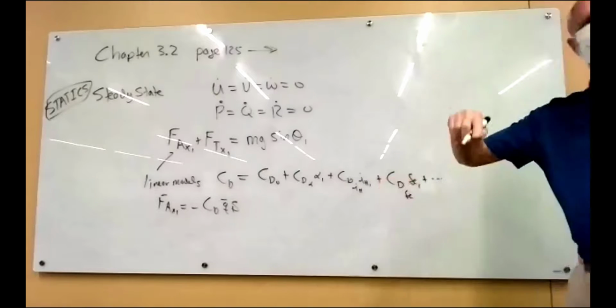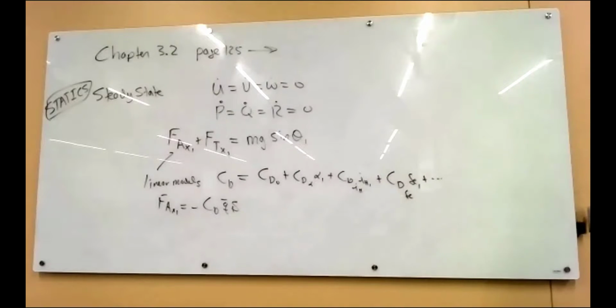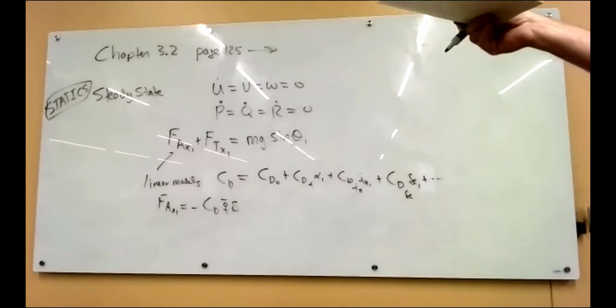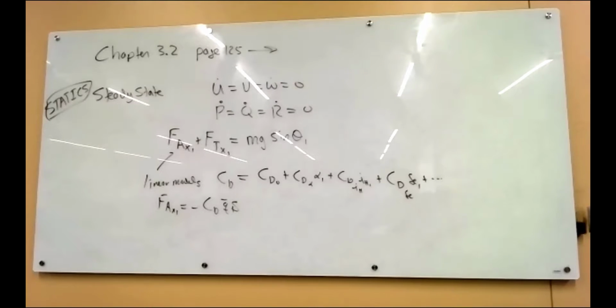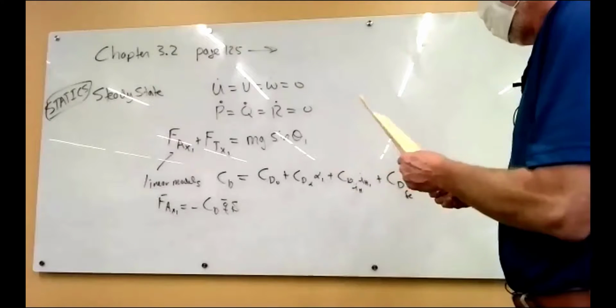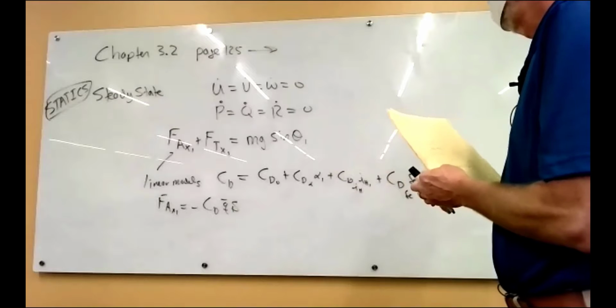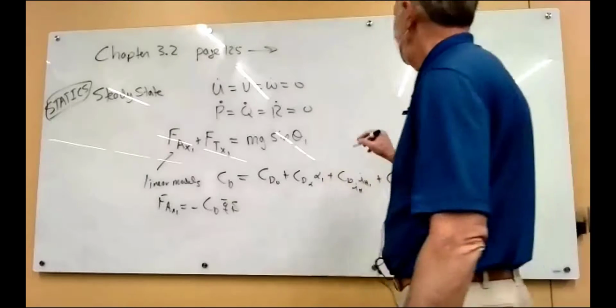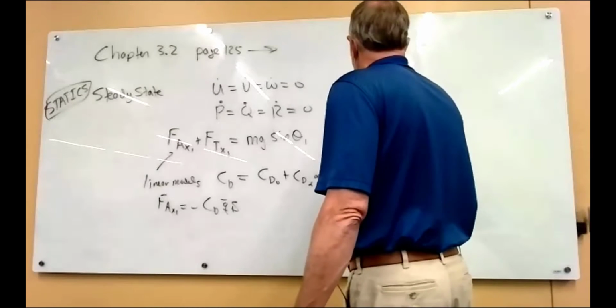And those are the matrices that we developed that are steady state forces and moments, longitudinal and lateral directional. And when we solved it for a turn or a pull-up or whatever, we would plug those models into the F's and the M's and the L's and the N's. So these are steady state equations. There's no differential equation at all. All of this stuff was algebraic.